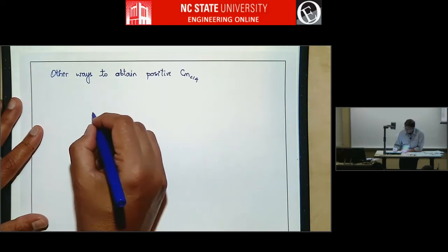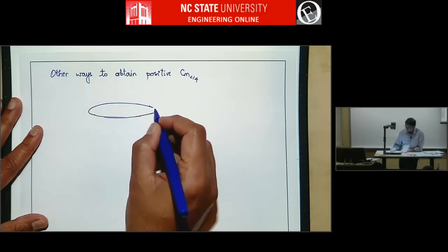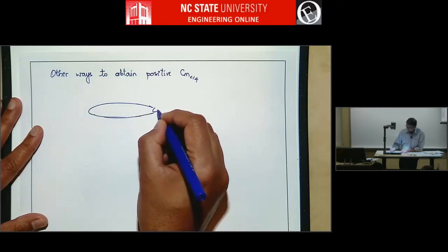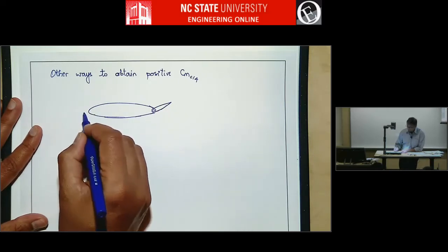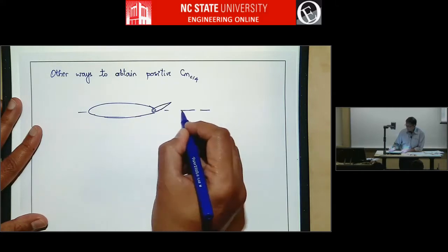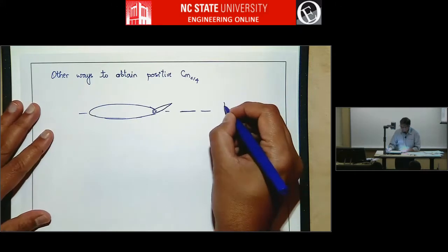You can have a symmetric airfoil and have upward flap deflection. So many airplanes, not many, but there are several airplanes where they do this. Most wings have some sort of flap in the back, right? So if you design a wing with a flap and aileron, and you want to make it a flying wing, you can turn the flap up. So TE flap up.